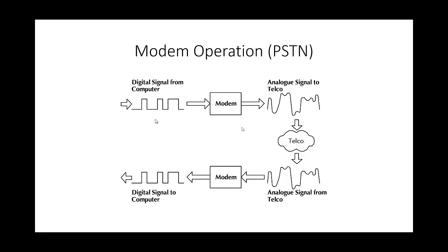Fast data transfer over voice-grade telephone lines is not possible, as the bandwidth of these lines is limited to the 300 to 3000 Hz range. This is adequate for reproducing conversations, and limiting the bandwidth of each conversation allows more of them to be multiplexed over the trunk connections between exchanges.